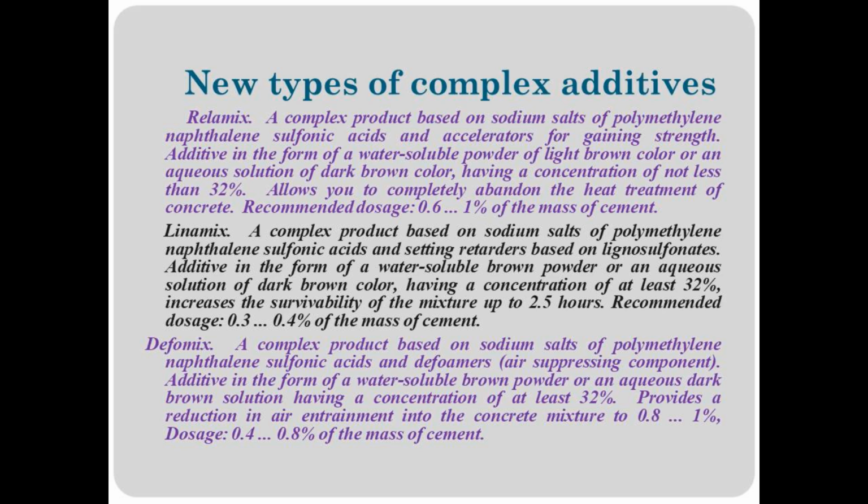Linamix. A complex product based on sodium salts of polymethylene naphthalene sulfonic acids and setting retarders based on lignosulfonates. Additive in the form of a water-soluble brown powder or an aqueous solution of dark brown color, having a concentration of at least 32%, increases the survivability of the mixture up to 2.5 hours.